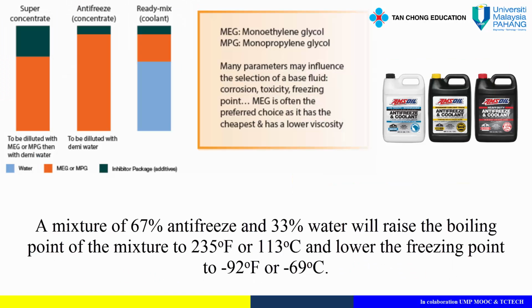A mixture of 67% antifreeze and 33% water will raise the boiling point of the mixture to 235 degrees Fahrenheit, or 113 degrees Celsius, and lower the freezing point to -92 degrees Fahrenheit, or -69 degrees Celsius.